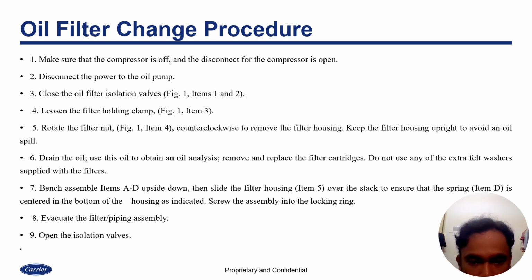Next is to drain the oil, and then the oil is to be used to obtain an oil analysis. Remove and replace the filter cartridges. Also, do not use any extra washers supplied with the filter. Next step is to bench assemble items A to D upside down.